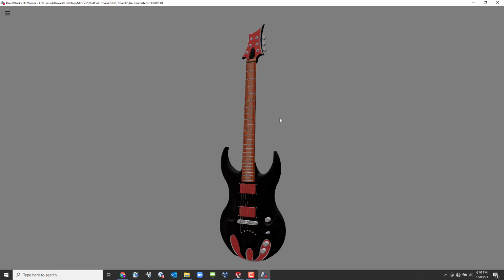You can, but it's never been my recommendation. Most of the time with DriveWorks, we're making an independent model from the original. If you don't have that particular configuration, using that word in the machine sense rather than the SolidWorks sense, it will save off a copy of all those files until they do assembly and drawing. But it can definitely push a config into a file.